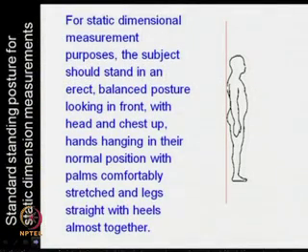Now, standard standing posture of static dimension measurements means that for static dimensional measurement purposes, the subject should stand in an erect balanced posture, looking in front with head and chest up, hands hanging in their normal positions, palm comfortably stretched and legs straight with heels almost together.